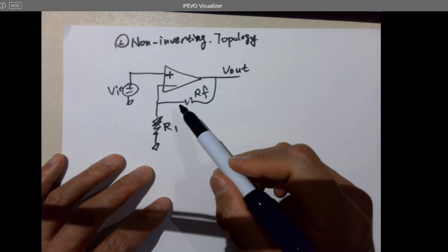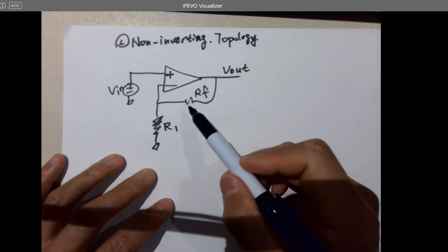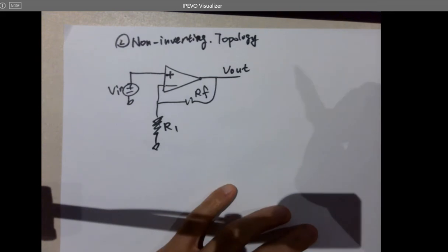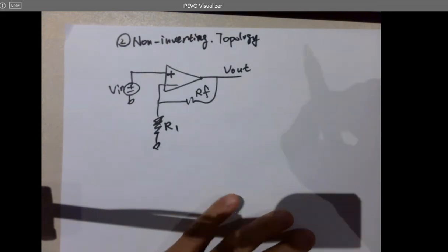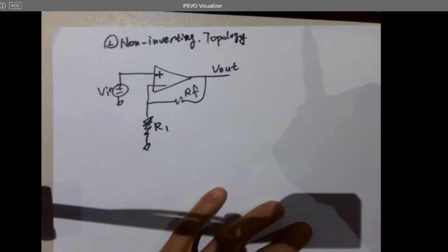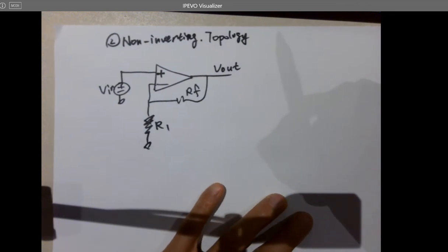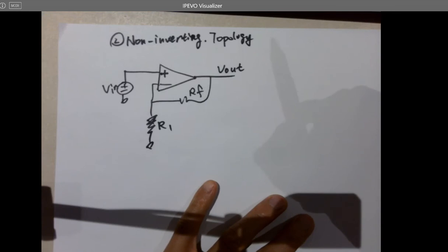First, we're trying to derive the voltage gain. So what we are doing here is we are trying to design an amplifier to amplify what? Voltages. Why do you need to amplify voltages? Because some of the voltages are tiny from the sensors, like millivolts, and you want to fit that range into your ADC.